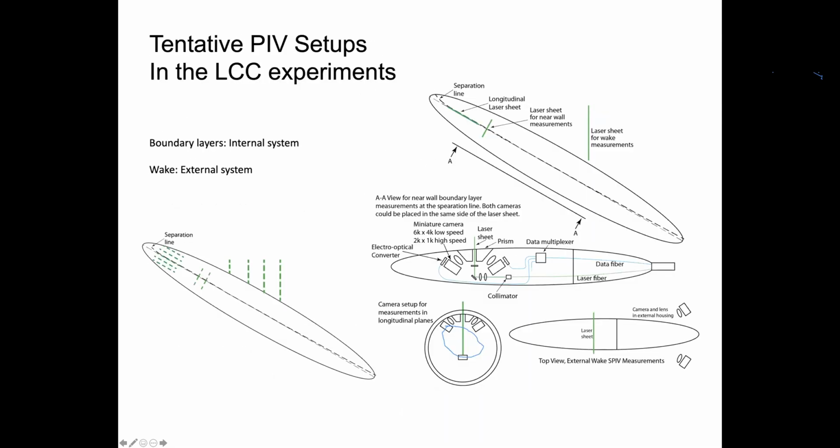Anyway, so I started working on different concepts of how to actually perform the PIV measurements, and at this stage, conceptually start accumulating the equipment. I will show you first the basic idea: we can record data with light sheets that are aligned with the axis of the model. This is easier to do. I'm talking about flows that are located very close to the surface.